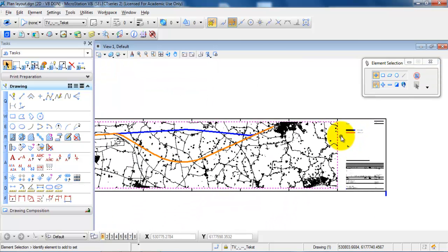The next thing I will show you is just how you hide the frame that we have right here. It's a frame that illustrates the border for the technical map or for our drawing, but we actually don't want to print this frame right here. In this case we can see that the frame is located in the level called TCR clip. So in order to hide